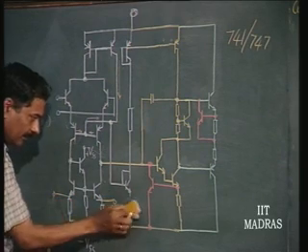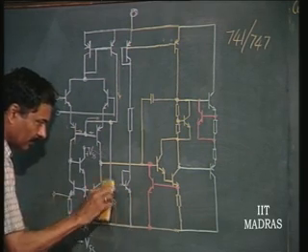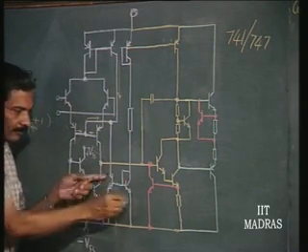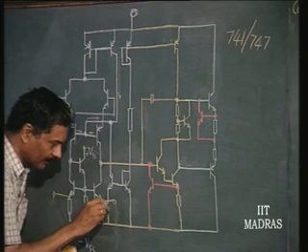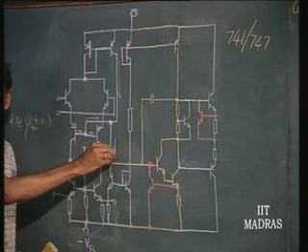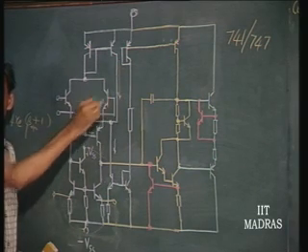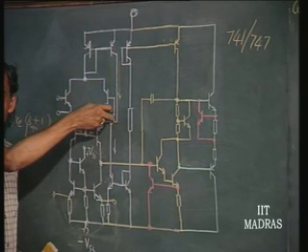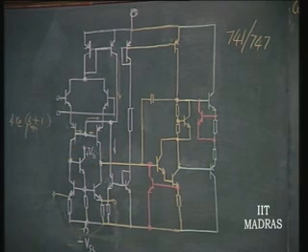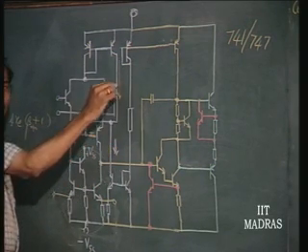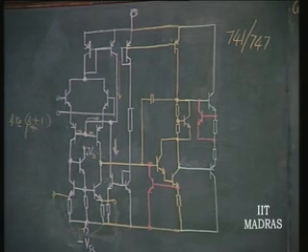Yeah, I think now you can see there is some change, mistake. This is the low valued current mirror, where we have to now put a resistance in the emitter. So, this is the low valued current that is generated. That low value of current is used in generating the feedback currents. These are the two feedback currents. This is the base current, and this is the total collector current getting reflected here. So, that means the emitter current of the whole thing is getting fixed by feedback now. This current shall become equal to this plus this, which will determine the operating input current of the input stage. Is it clear or not?